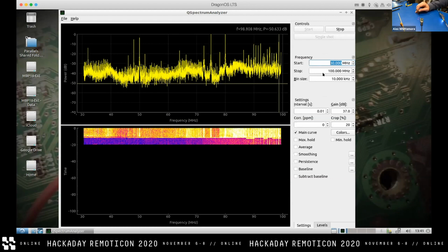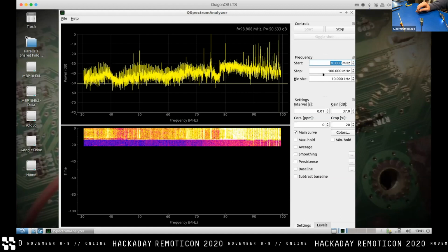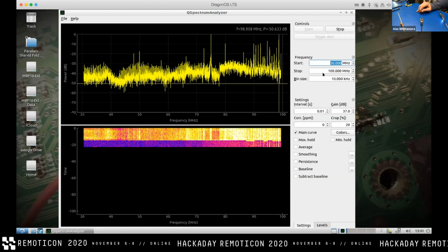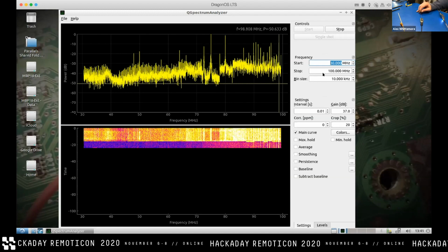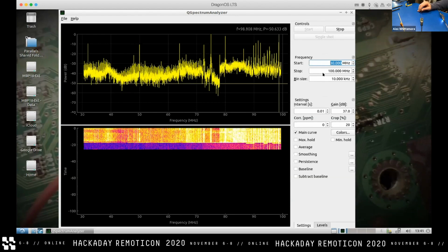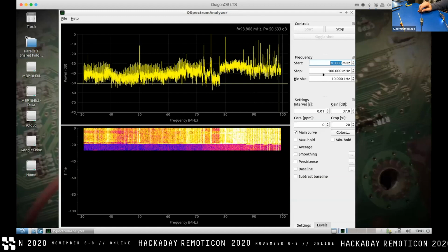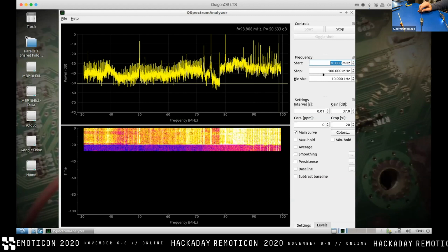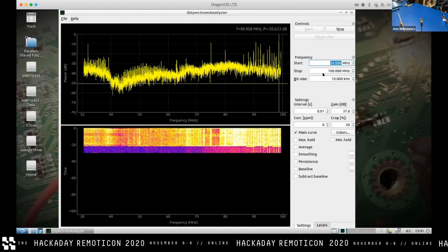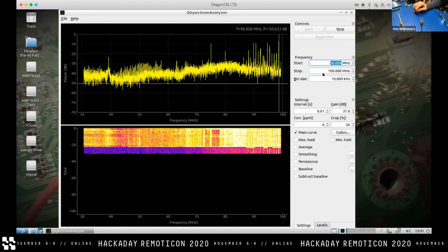And obviously the disadvantage of doing this, and this is where your cost constraint is a trade-off between features and convenience and money, is that this updates like one chunk every couple of seconds. This tells us what's going on everywhere in the spectrum, but not everywhere in the board. If I wave my wand around, whatever section of the spectrum it happened to be sampling in that time will get caught. So I'm gonna click it and then take my sample away, and we're gonna see weird sections of the spectrum have changed and not all uniformly.